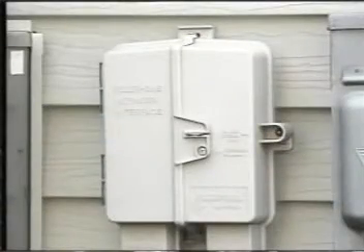And now what you'll find is usually a fairly large metallic box with limited access, some sort of a control of a screw or a recessed holding device that can be opened by the customer, and they will have access to part of this interface box which controls the inside wiring to their communications equipment. Another portion of the box, which has limited access to telephone company equipment, will provide access to the network. This allows a telephone company technician to be able to test the line from the customer facilities back to the central office, and allows the customer to check from the interface box back into their equipment. So it provides testing in both directions by the interested parties.